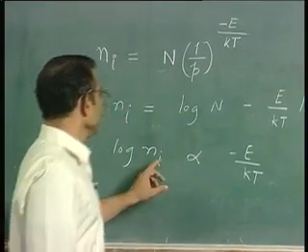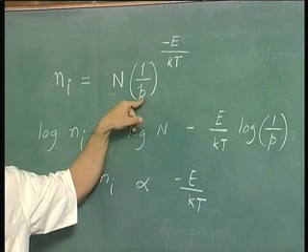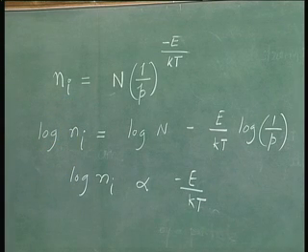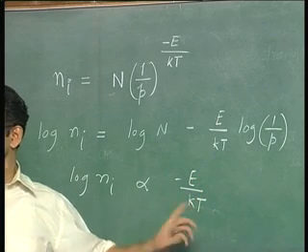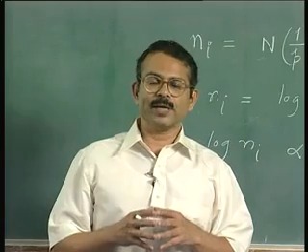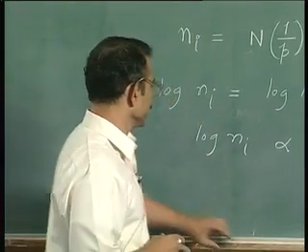What is the problem here is that we do not really know what this P is, we have no way of calculating P in the model. So what we can get is a broad behavior. We cannot make accurate calculations, but we have shown using this model that Ni on a log scale varies as reciprocal of temperature, and the behavior is linear when we plot log Ni versus 1 by T, which is not a small achievement at all. To get a more accurate description where we can make calculations at any temperature, we must go to the band model, which is the topic of discussion today.